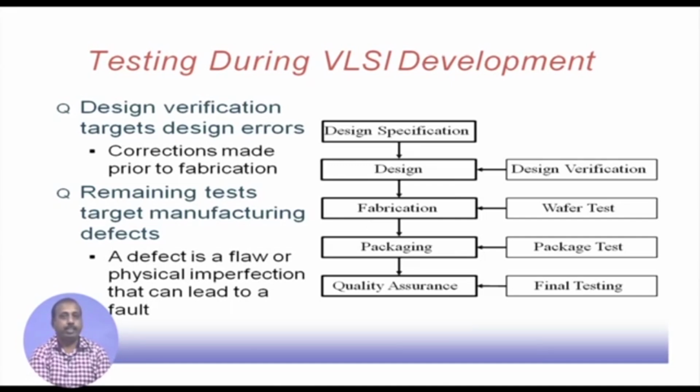So, we have fabricated the transistors, the links between them, etc. Now, at that point of time, we need to check whether the transistors have been fabricated properly or not. As I was telling, if we can detect this wafer to be faulty at this early stage, some transistor to be faulty, we can remove this transistor from our connection pattern, and maybe we can use a substitute transistor for the purpose. So, at this fabrication level we have to do a testing which is the wafer level test.